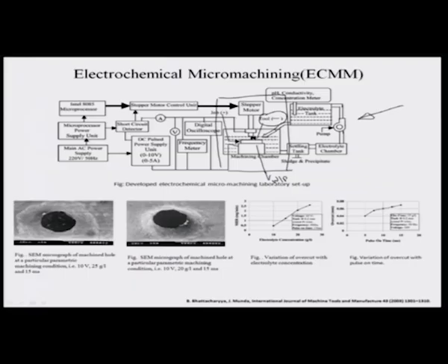There is an electrolyte which is being pumped through this nozzle right here, okay, into the workpiece zone, and of course there is a flow handling system, so you have a settling tank for the sludge to get settled down, there is a filtration system, there is a pump, there is electrolyte chamber, which causes the electrolyte to recirculate. There are different controllers here. There is an Intel 8085 microprocessor which this group is using for setting up such a system.